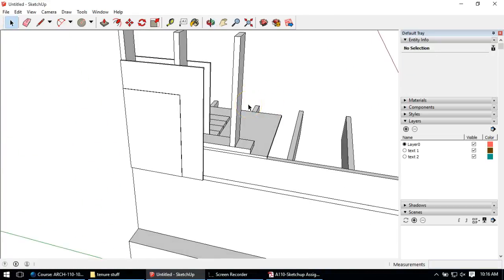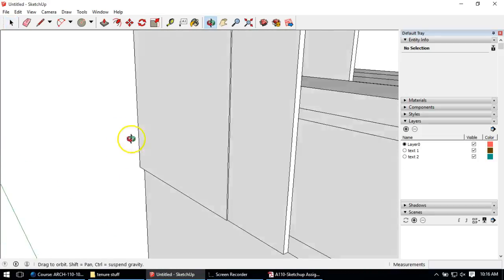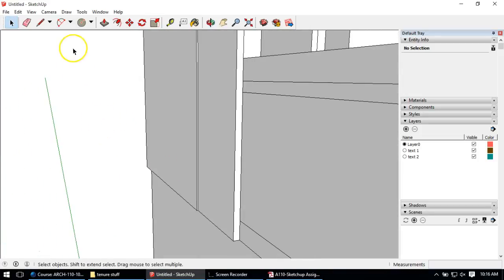And then we've got 5-inch shingles, looks like 13 wood beveled shingles with 5-inch exposure. So they're going to obviously have to be taller than that. But again, we don't need to draw what's sort of hidden, so we only need to really draw the 5-inch segment. And so to do that, I'm going to click here. I'm going to come out an inch, we'll see how that looks. I'll come up 5 inches, and I'll come back all the way to my inch.